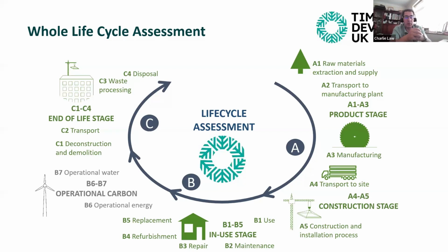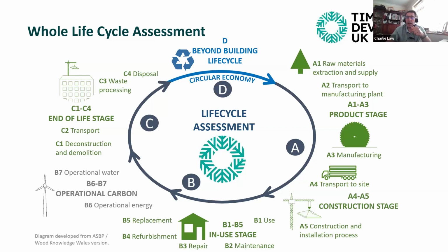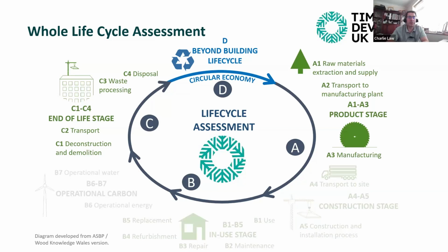And when we talk about disposal, we're talking about landfill there. In that situation, there is also what we call stage D, which goes beyond the building life. The idea of stage D is that benefits of timber can be added here, for example, avoiding the use of virgin product in lieu of recycled product, or using biomass instead of a fossil fuel when you're generating energy. So those are the types of things that you can put as benefits. They don't form part of the overall calculation for the EPD, but they are those additional benefits of that product or material.